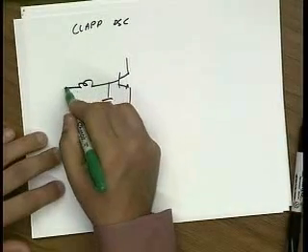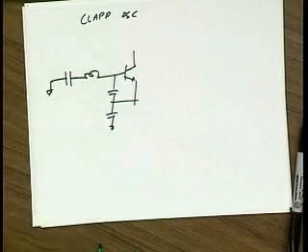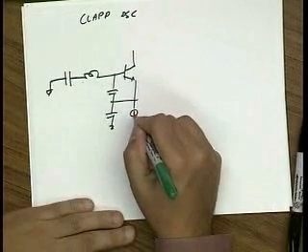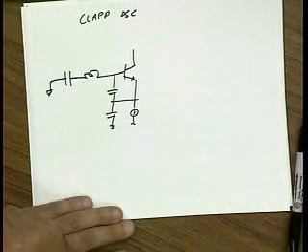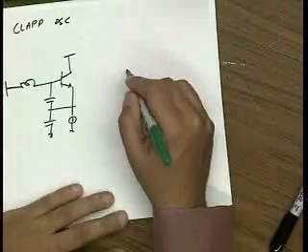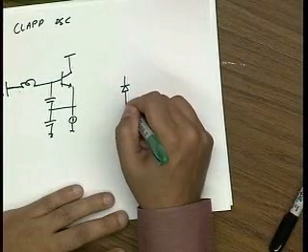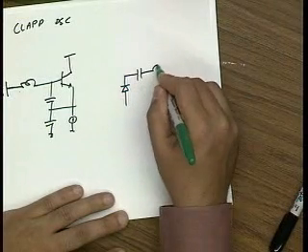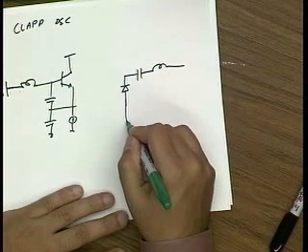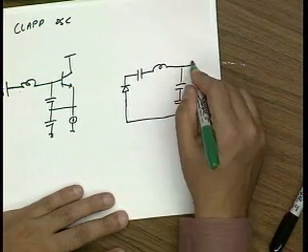So here I'm going to put another capacitor here and ground it, and you say, well, big deal, why would you do that? Well, this is a nice way to build a variable oscillator. This isolation that I get for free, I can use to introduce a varactor.